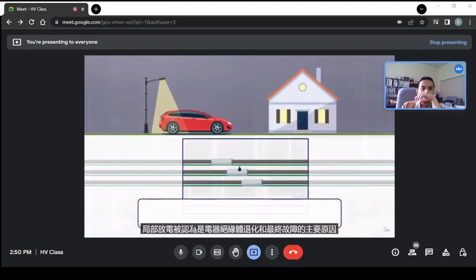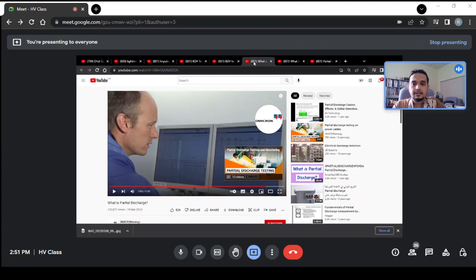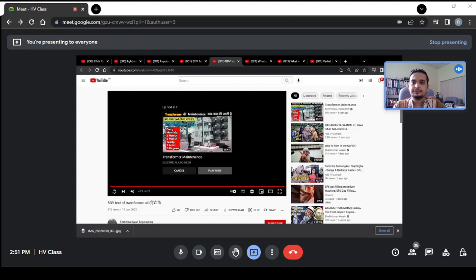Based on what we know here, about 80% of high voltage failures are from PD activities, partial discharge activity. So we really need to measure and monitor to ensure the reliability of the insulation material remains in good condition. That's about the PD, and then I'll just show you a couple more videos here, one or two before.